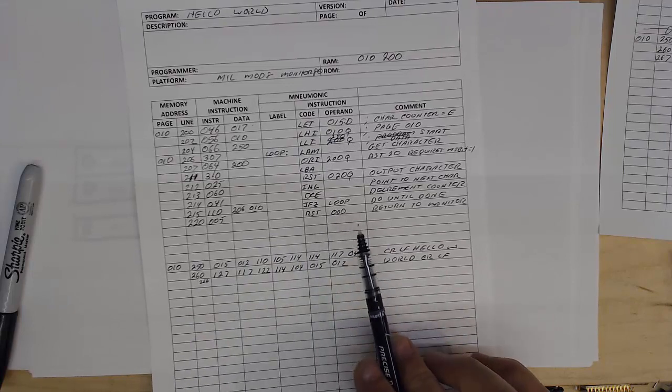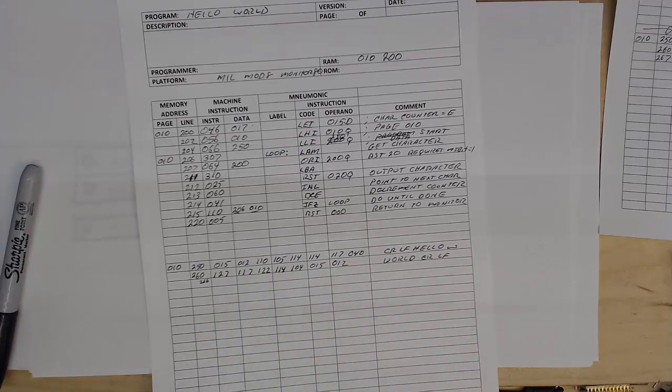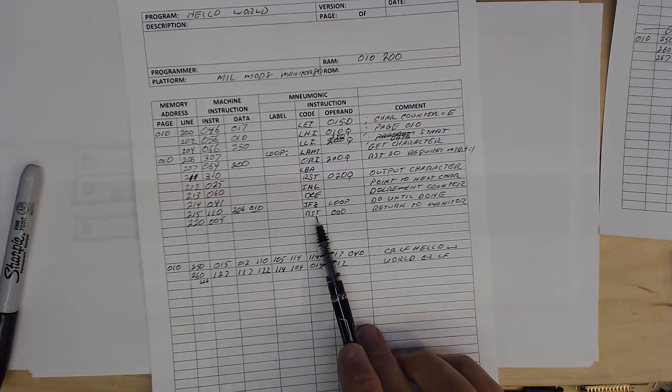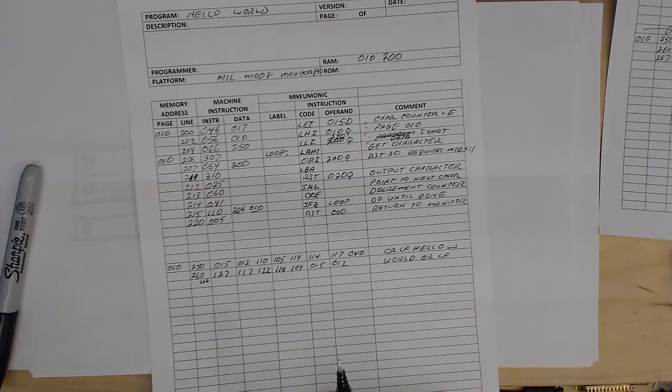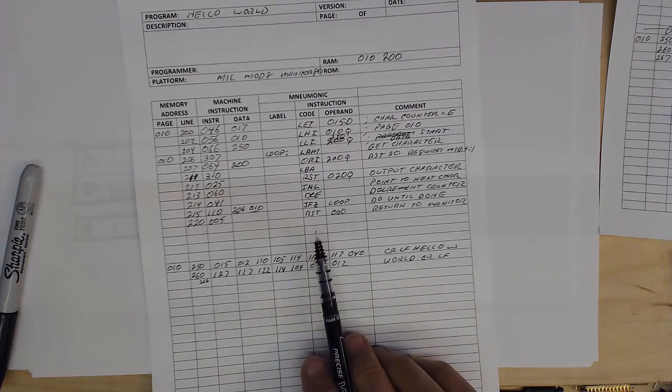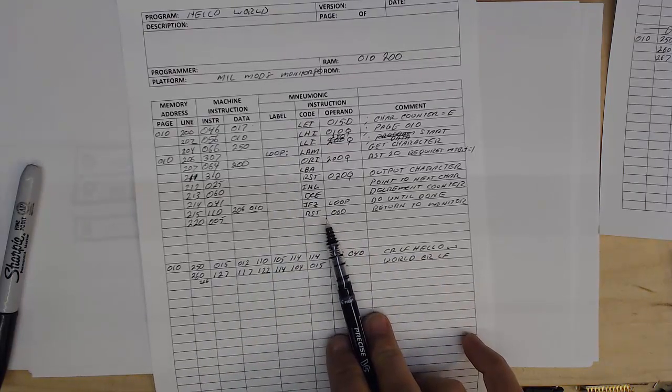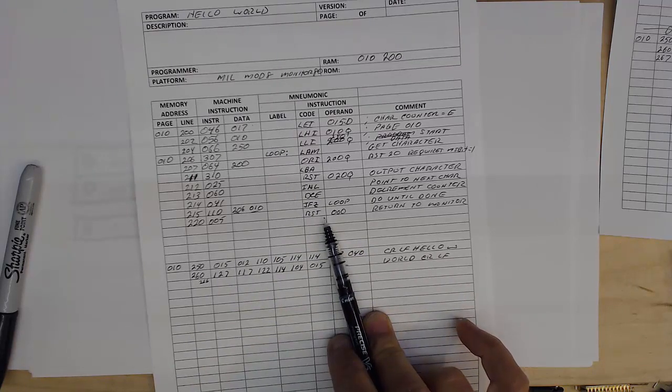There's also the new set, which looks much more like the 8080 instruction set. So when I'm programming 8008, I intentionally use the old set, and when I'm using the 8080, then I use the new set. But just so that you know, you will see some 8008 code that has the new mnemonics, and assemblers were put out to support the new mnemonics in order to make it look more like the 8080.